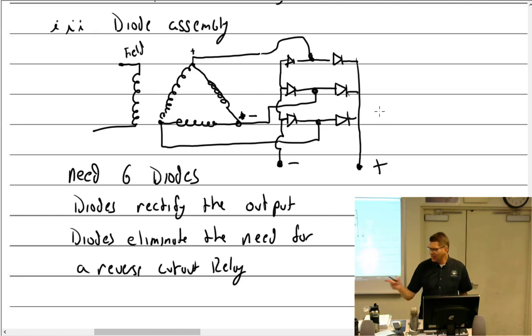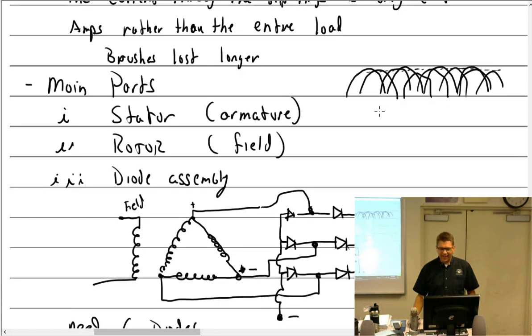See this guy right here? It's to help him out especially. So when you use a capacitor in DC, what did I say that helped? Smooth stuff out. So on the peaks, it's going to absorb the peak, and on the valleys, it's going to give back out. So where it looks choppy like this, well, when I got all done, it looked pretty much like that. So it looked pretty good. So I just needed to add a capacitor, and then it's going to be all better.